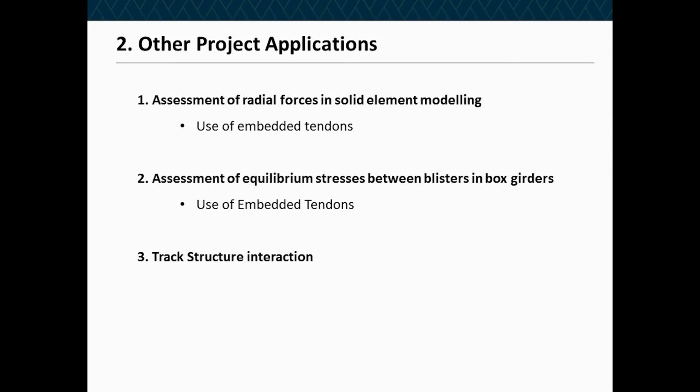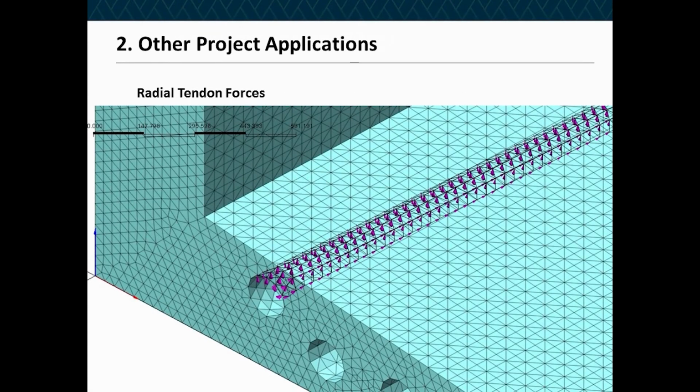All three of these are related to projects where we were asked to come in and investigate what had happened. On one of them, on this first one, the contractor had stressed the tendons and a number of the joints within the segments of this post-tension concrete bridge. He had bursting of the concrete. It actually just exploded during stressing of the tendons. Now what we found out was that the tendons had floated during the casting process, and you ended up with a tendon profile or a duct profile that looked something like that, and as a result there were localized pressure points which exploded in the concrete.